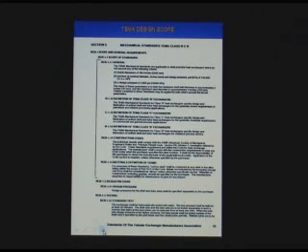Roll bonding attempts to do that. It's a good way to do it, but I do not have any photographs; if you do a micrograph and chemically etch it, and then look at an explosively bonded clad plate, you will have a very thin layer between the alloy and the carbon steel. You'll see a transition between the two materials, whereas on roll bond you'll see a much more defined fusion layer. So explosion bonding is a very, very good way to go.